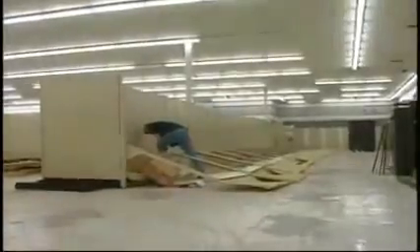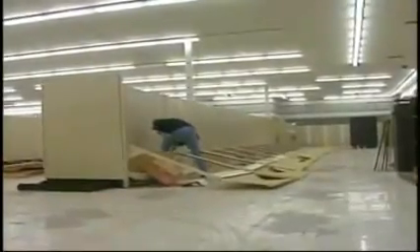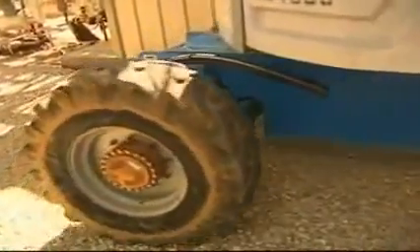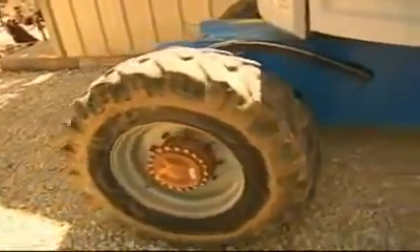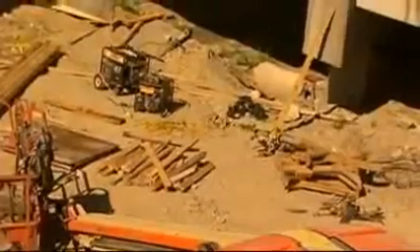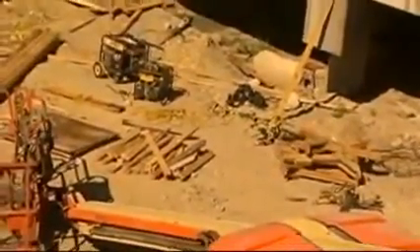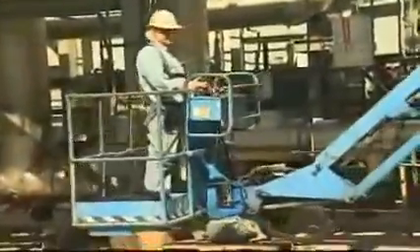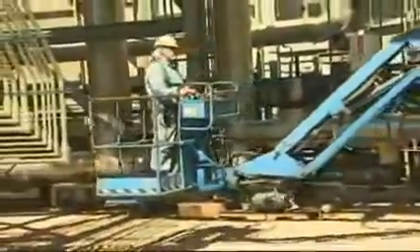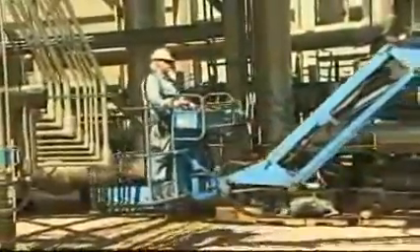It is necessary to always inspect the work site prior to using the lift. The ground on which the lift will be used needs to be solid and as level as possible. Do not use a lift on unstable ground. Hazards that may create dangerous driving conditions, such as overhead power lines, holes, drop-offs, bumps, lumber, tools and debris must be identified, and procedures to avoid any hazards made known to all employees.